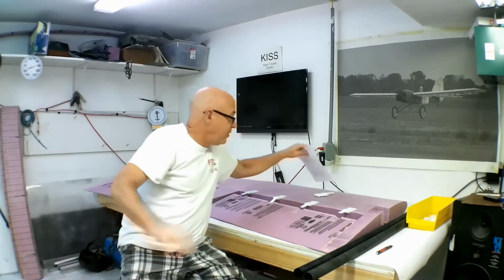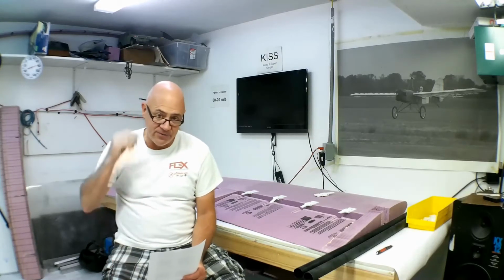So you've got the two different types of wing construction, okay? And when I talk about the construction of the wing, be it foam or be it built up, in your plans, in your drawings, when you're engineering this, you need to kind of understand what works and what doesn't work. I've had a lot of people say, Damon, what is the math you use in designing a wing? There's no math I use. Well, I don't want to say that. There's not any structural engineering math that I use. What I do is I'll build a mock-up of a spar, I'll take it to my garage, and I'll put loads and weights on it and see what the spar can handle.